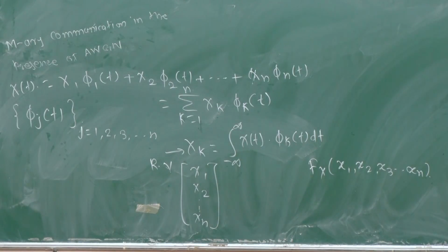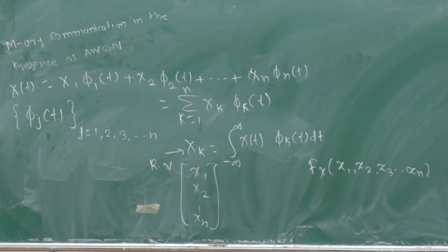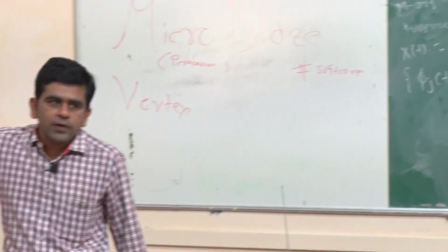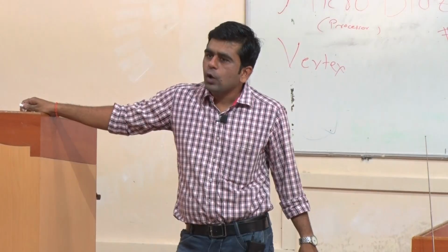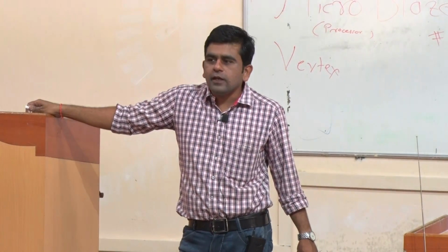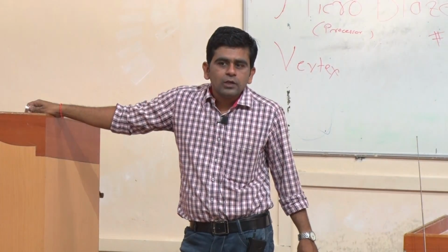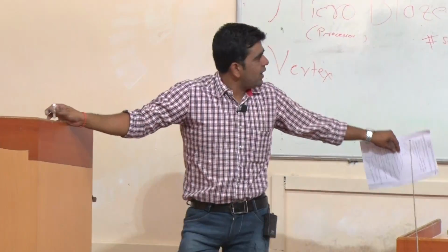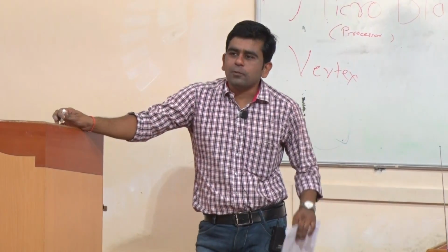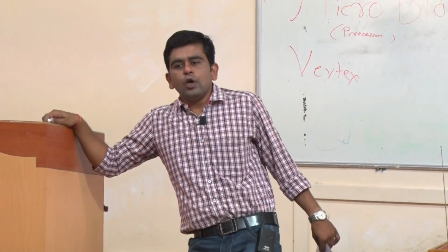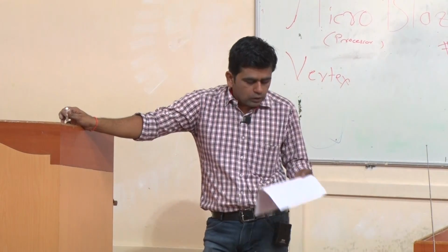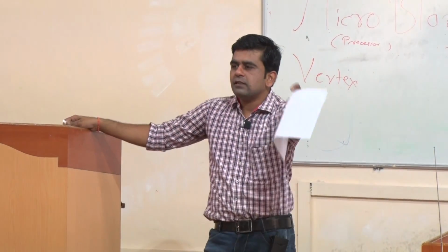We will get S of t from your transmitter. At the receiver, S of t plus some white Gaussian noise is going to add in your message signal. So x of t is equal to S of t plus n of t. This n of t is a totally noisy term, and this is your random process. So in this example we have considered x of t as a random process. Now, to be specific, we have to consider noise as a random process. So write down.